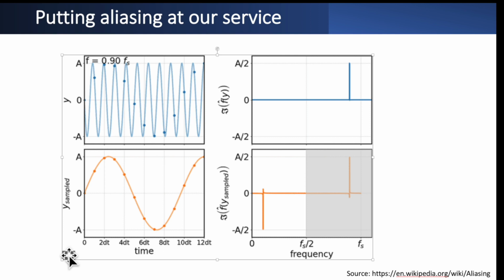So normally we would not like that to happen, and we would take measures to prevent it, either by simply choosing not to sample frequencies that are higher than half the sample frequency, the Nyquist frequency, or by adding an analog filter before the sampling process, or using oversampling or some other measures. But today in my video I'm going to take the side effects of aliasing as a tool, because they are predictable in nature, and by means of this predictability we can learn some interesting things about what's happening inside the RTB oscilloscope.